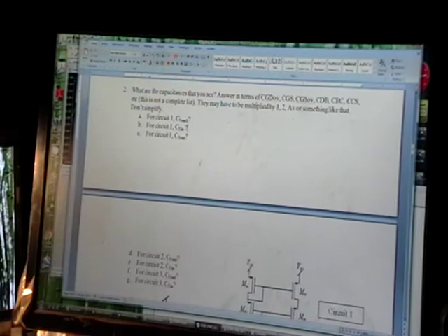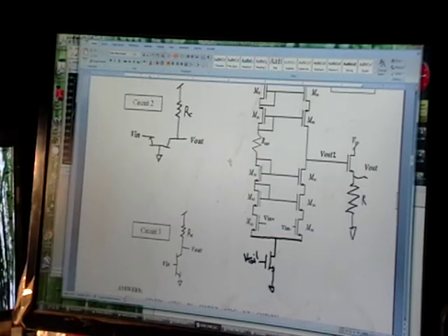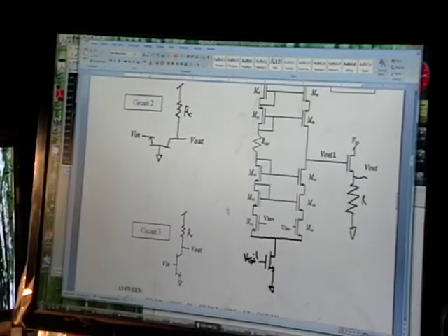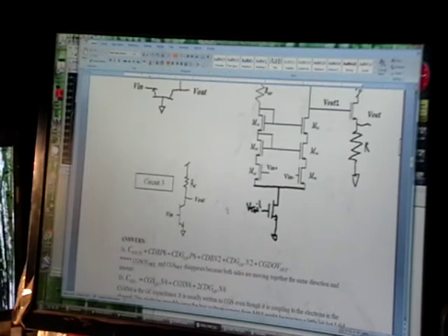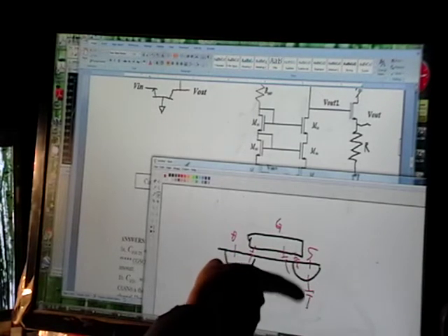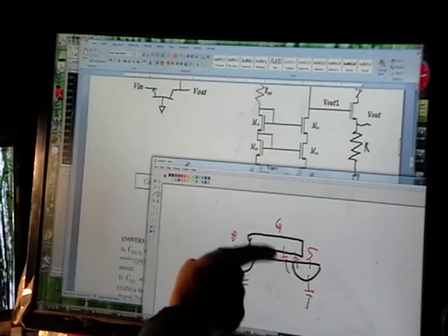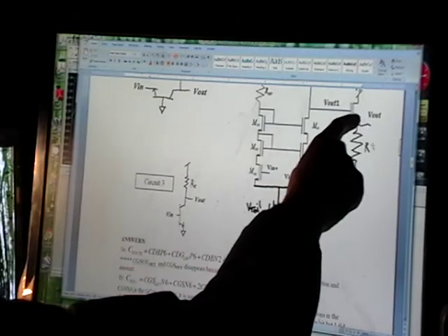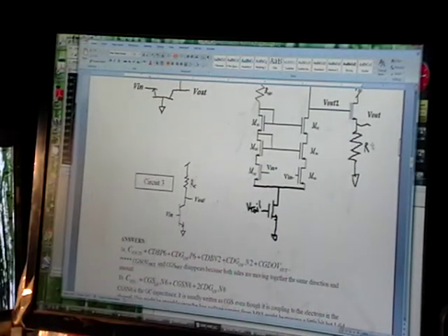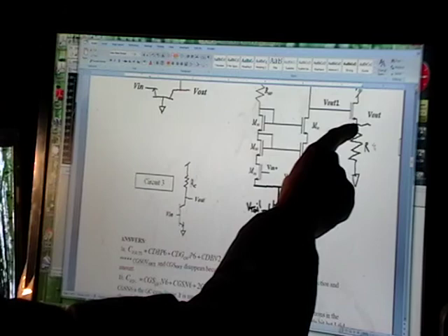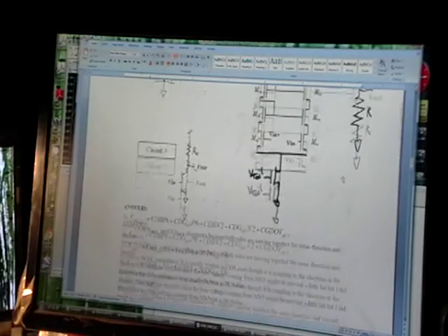The third one is circuit 1 V out. Okay, so the capacitance on this node right here. Okay, so this is a follower again, and you're sitting on the source, so you go over here and you see, okay, I'm sitting on the source, I've got a source bulk, I've got source gate overlap and a source gate. Okay, so you go over here and you say, okay, source bulk is at ground, so that is just whatever it is, and then you've got the capacitance from the gate and source, the 2 capacitance across there, overlap and just the regular one.